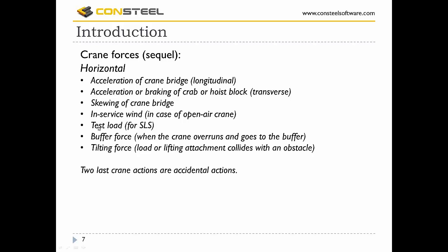We have a test load for serviceability limit states, and the last two force types are the accidental actions: the buffer forces when the crane overruns and goes to the buffer, and the tightening force when the load or the lifting attachment collides with an obstacle.